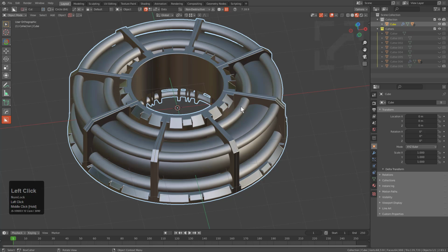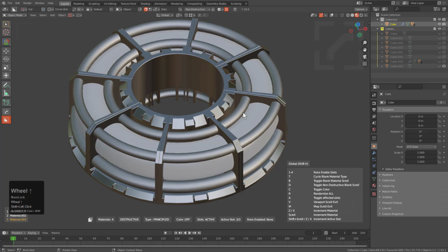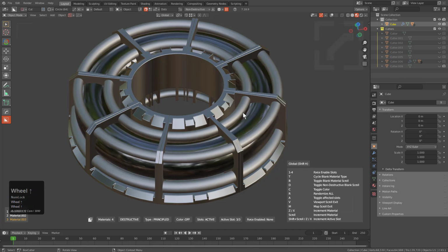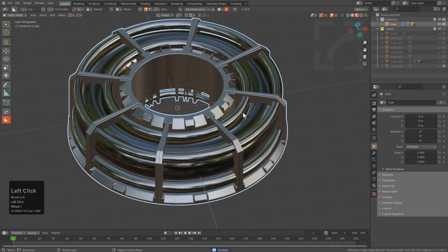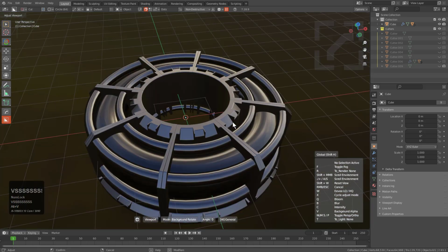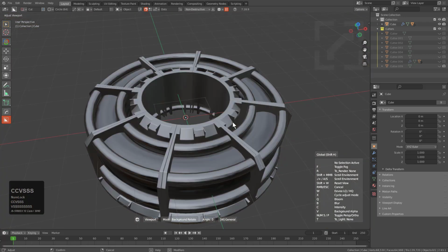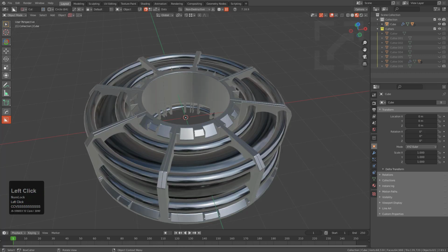And when we look at the render result, we see that there's probably a little bit of scrolling to do. So let's just shift click on material scroll, which means we're just getting in and replacing the particular graph, but we're keeping the index. Not needed, but we can also shift scroll to jump to the next material in the stack and begin scrolling it as well. And now I'm jumping to the main material and we're just scrolling it to a material that's a little more acceptable. So we can press Alt-V, press S to jump through our environments till we find one we want. We can press V in order to turn it off in case we want to just look at just the object. But just like that is a little bit about join and smart apply with twist on the fly and just having a little bit of fun with it in bevel.